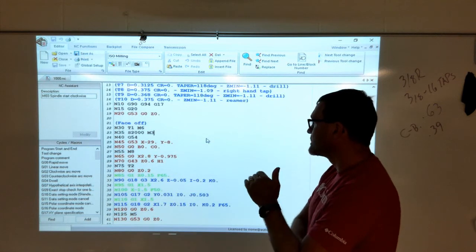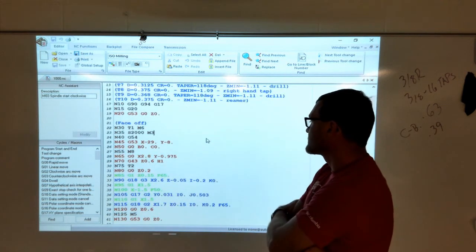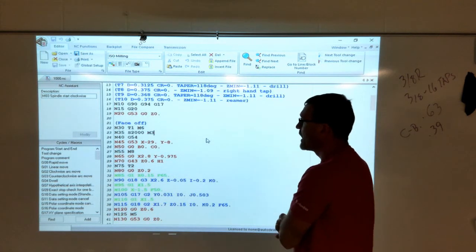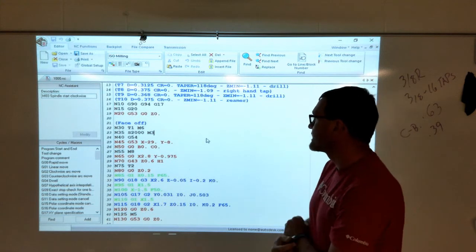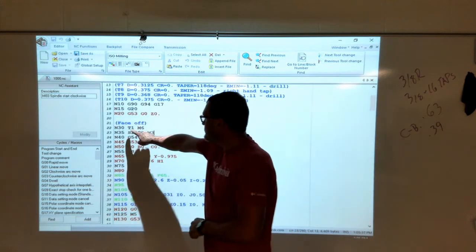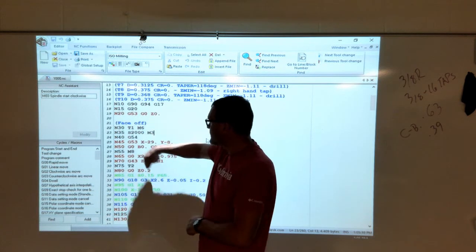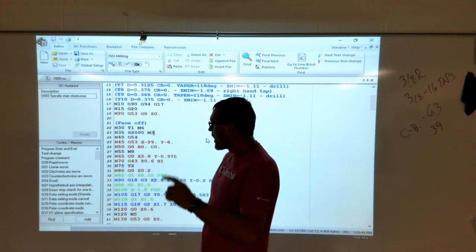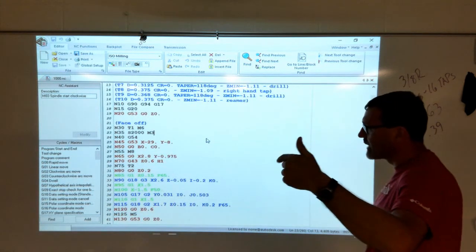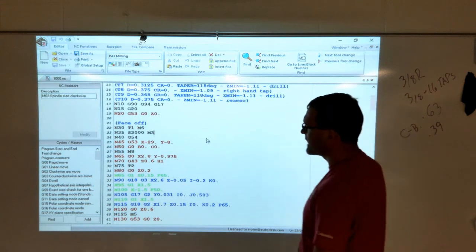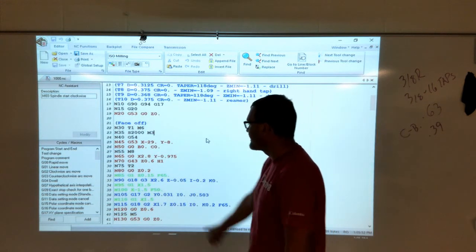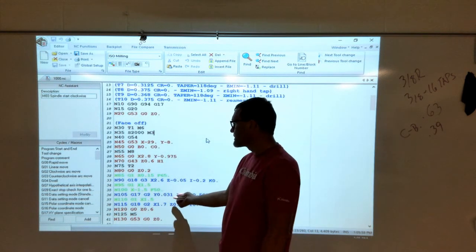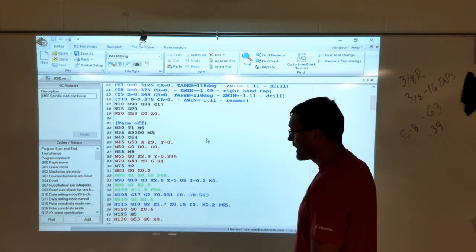If it just annoys you, then you can go back into the post processor and make adjustments for that. The other thing that's going to throw some people off is, depending on the type of tool changer the machine is, it's calling up tool 1. So we've got M6 tool 1 there. You can switch those around too if you want to. Here it has T2. All that's telling us is put tool 2 in standby. So if we have a chain or a tool changer that allows us to have standby tools, we can go ahead and do that. But you can see tool 1, H1, if we're using cutter compensation on any of our tools, it would also then be D1. But we're not in this one.